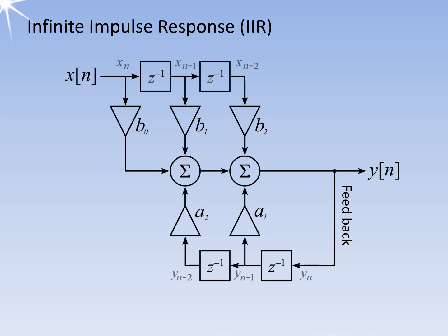The implementation of IIR filters is more difficult due to their feedback mechanism. Digital IIR filters have a significant advantage over FIR filters because of their efficient implementation in meeting specifications for passband, stopband, and ripple. They can achieve such specifications with a lower-order IIR filter than would be required for an FIR filter with the same requirements.